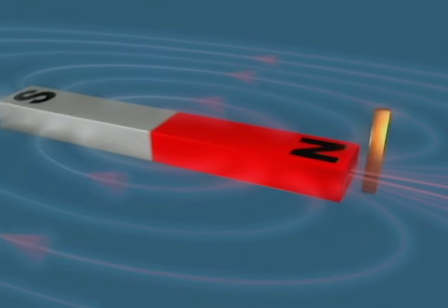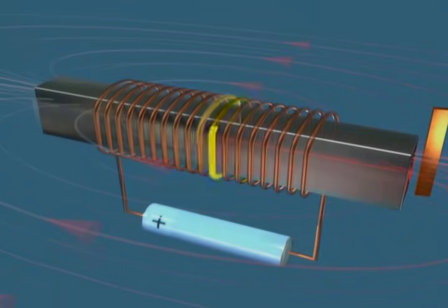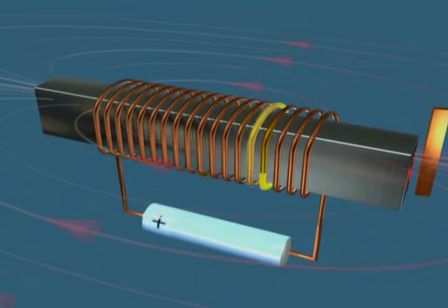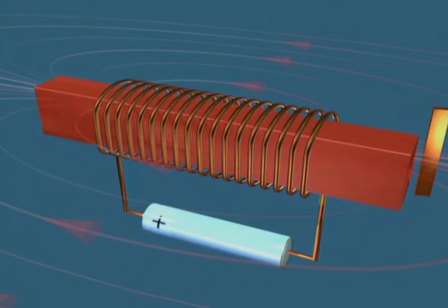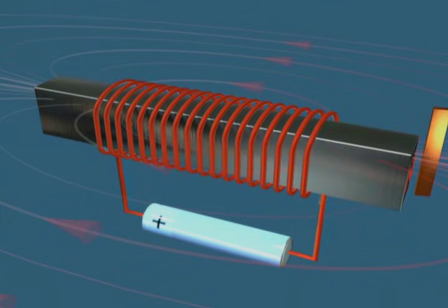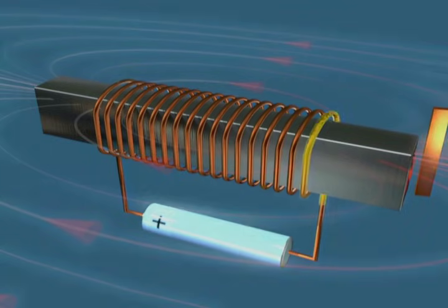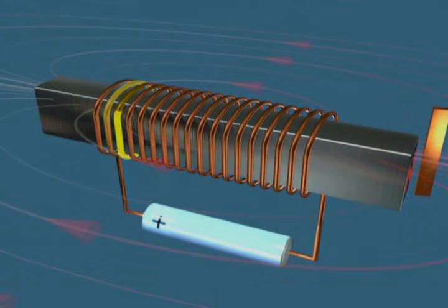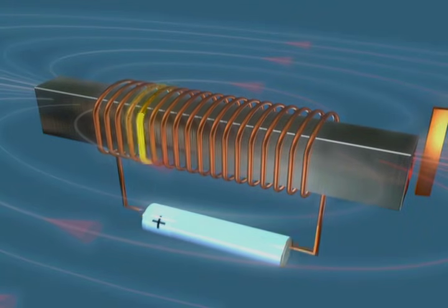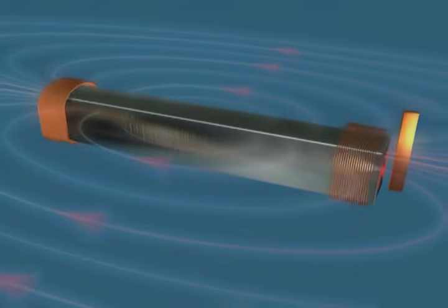Let's go back to our rotor. It creates exactly the same effect as a magnet, except that it is made up of electromagnets. An electromagnet is used when a very powerful magnet is needed. It consists of a metal core placed inside a coil of electric wire. When a current flows through the electric coil, a magnetic field very similar to that of a magnet is created. The main advantage of an electromagnet is that the force of its magnetism can be controlled.